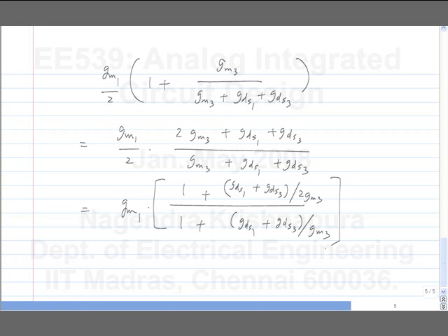Okay. But for all practical purposes, you can assume that the transconductance of differential pair loaded by a current mirror is the transconductance of one of the input transistors. Okay. Now you can do the analysis with everything combined together. You just put the 3 node equations and do it. You will get the same answer. Okay.